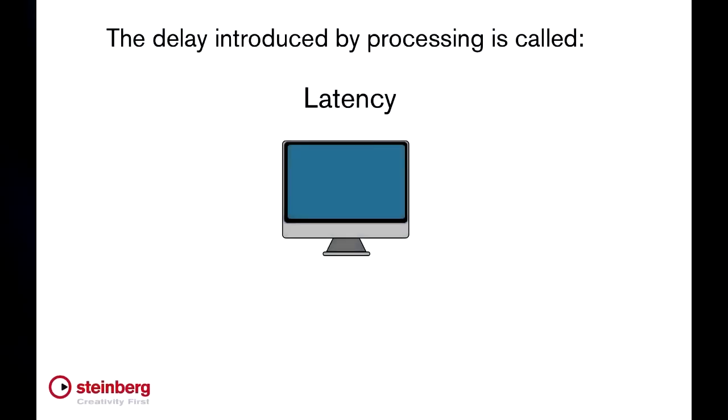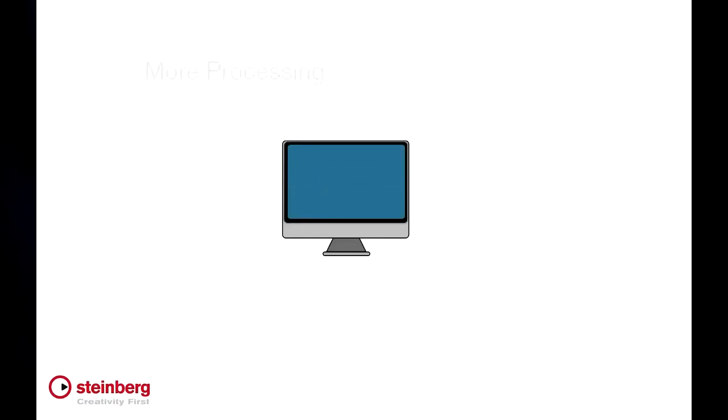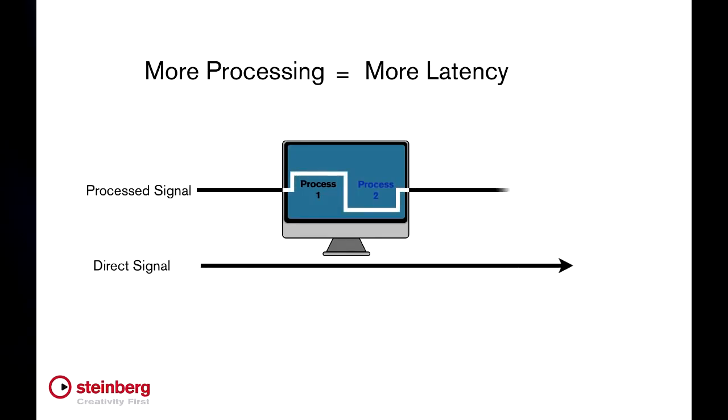And latency is the short period of time, usually milliseconds, that it takes for an audio signal to be processed by a digital system. Latency results from analog to digital conversion, buffering, and signal processing. The more processing you apply to a signal, the more latency you will introduce. Latency is primarily a factor when recording live audio. If the latency value is too large, the performer will hear a delay, similar to an echo, between the time they play a note and when they hear it in their monitors.